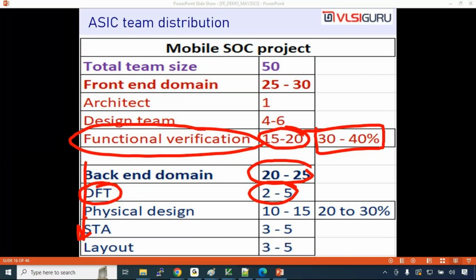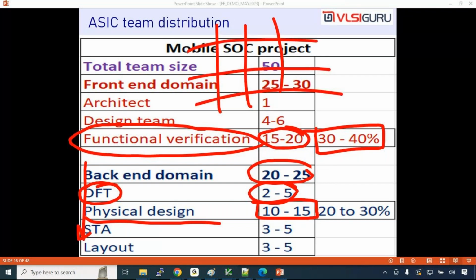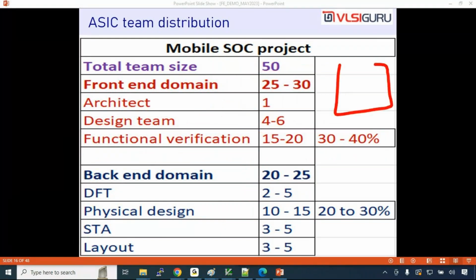Physical design is where again you need a lot of people, because they need to implement each and every block. What is meant by physical design is planning the area. I told you, right? In FPGA, we don't have so much effort, because in FPGA already you have the gate array. You have to put your gates onto the array. Whereas in ASIC, you have an empty paper where you have to plan everything yourself. That planning is called as physical design.